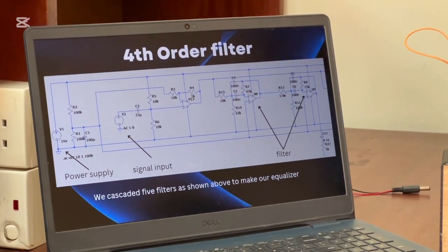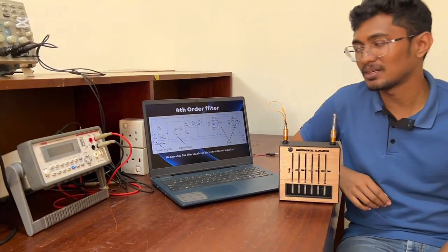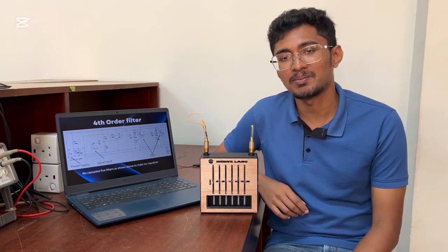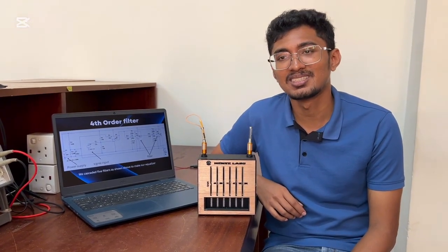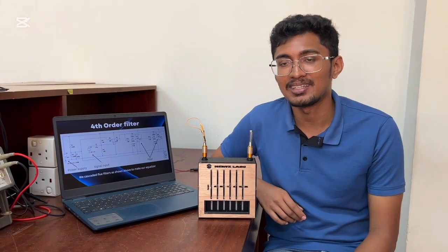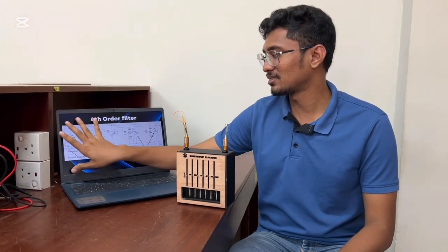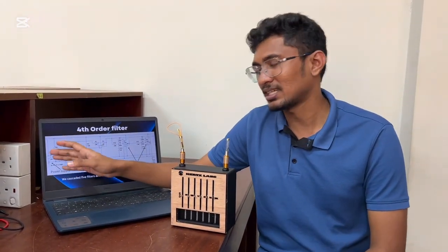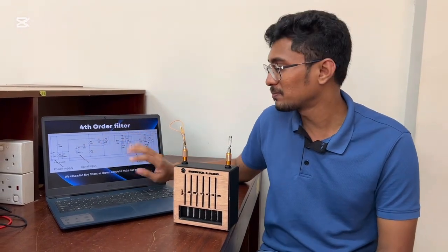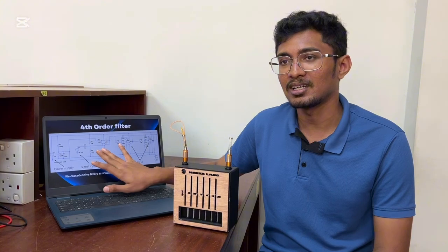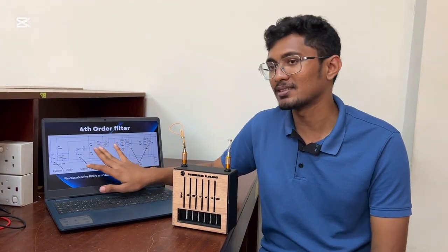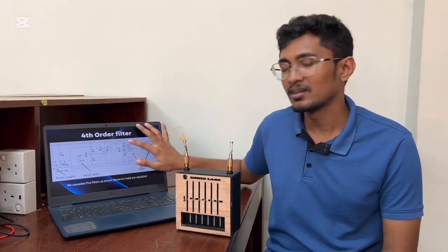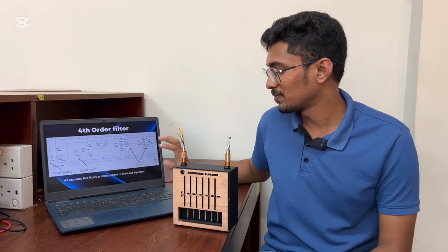We are using an 18 volt single power supply designed to power up our application, because dual power supplies are generally not used in day-to-day life. This is the part which supplies the power from the single supply design to power up these dual supply op amps. And here we have the input stage, which buffers and converts the signal into a mid voltage, and then a single pass band filter.